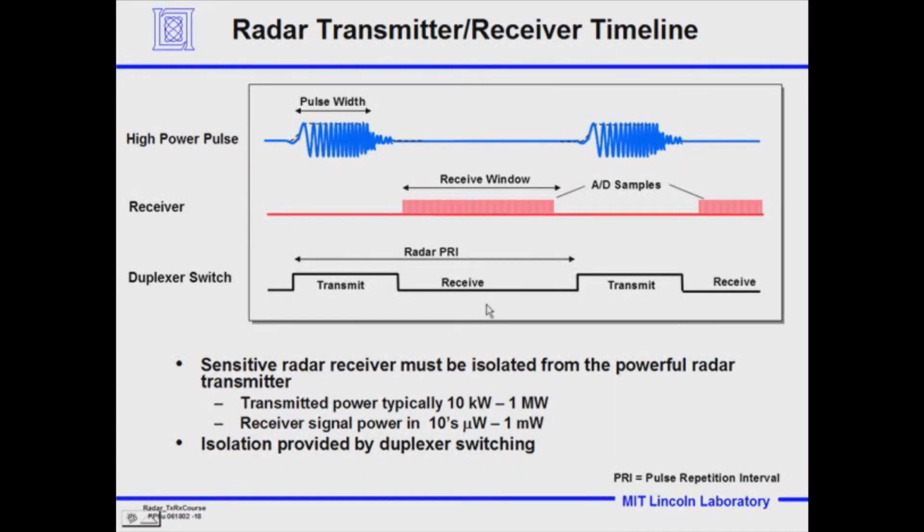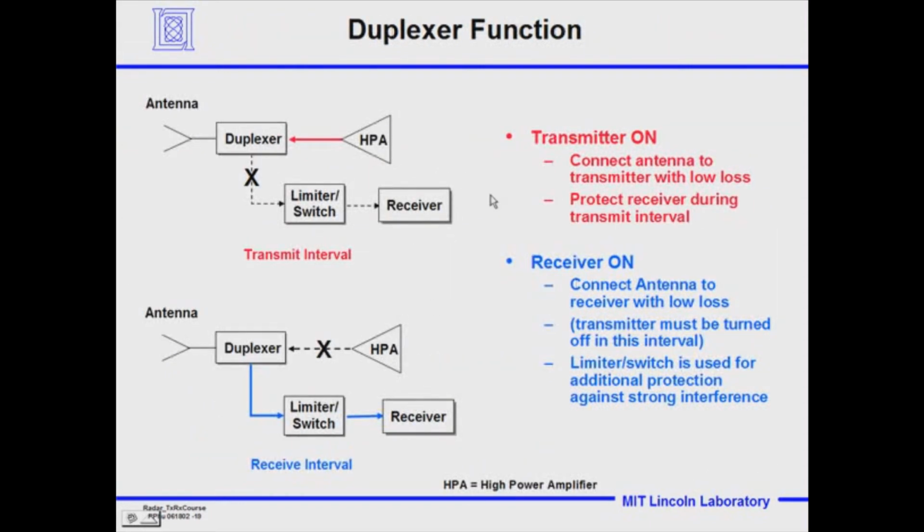If you remember back to the first lecture, we saw that in the Chain Home radar the transmitter was located at a different physical location by hundreds of feet. In those days, they weren't great at building duplexers, so they put the transmitter physically distant by hundreds of feet from the receiver in many cases. Okay? So the technology is not easy, to make something with 9 orders of magnitude of isolation between the transmitter and the receiver. So that's the very important function of the duplexer. Now let's just look at it in a little more detail so it can sink in.